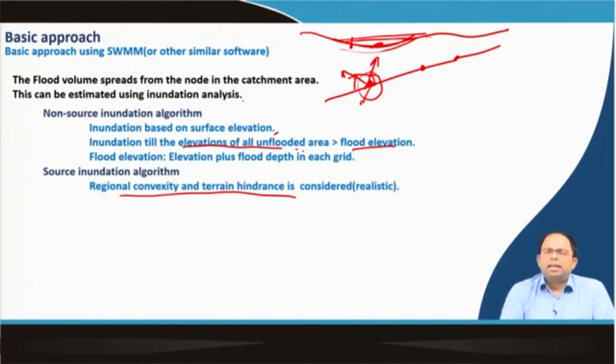So, we have learnt earlier when we used the DEM models that water flows using the D8 algorithm, that water flows in the direction which has got the highest slope. But sometimes water can flow proportionately to different directions based on the different slopes as well. So, if I consider only one direction flow, that is 1D. If we consider multiple directions and in different ways the water spread, then it is 2D.